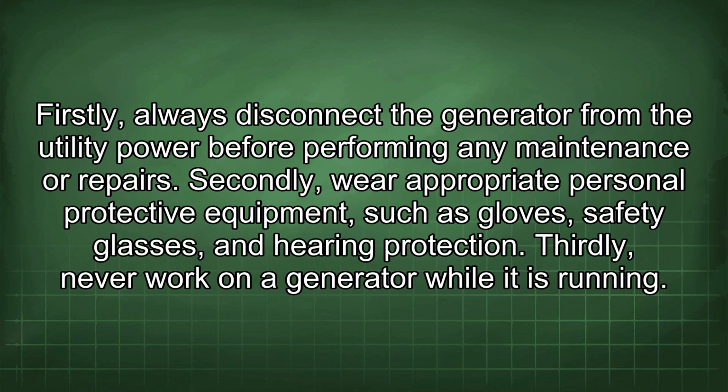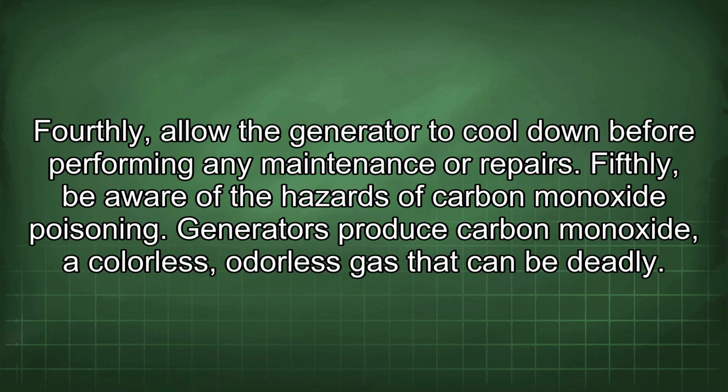There are several key safety considerations to keep in mind when working with generator systems. Firstly, always disconnect the generator from the utility power before performing any maintenance or repairs. Secondly, wear appropriate personal protective equipment, such as gloves, safety glasses, and hearing protection. Thirdly, never work on a generator while it is running. Fourthly, allow the generator to cool down before performing any maintenance or repairs.